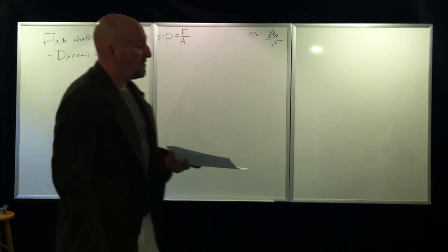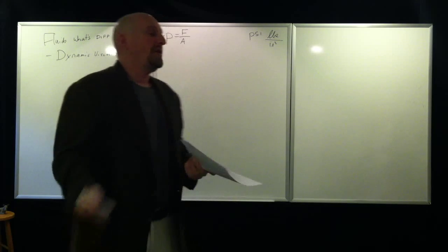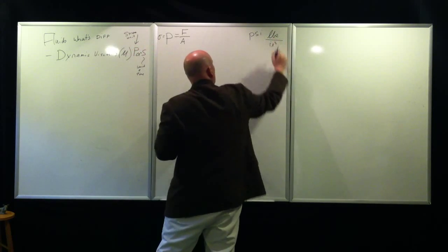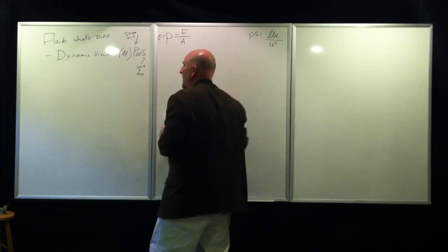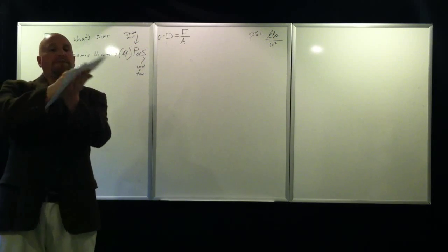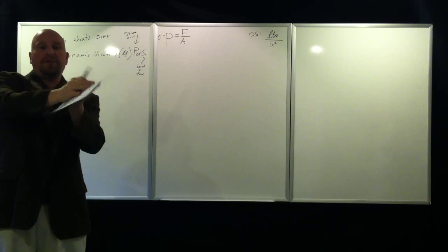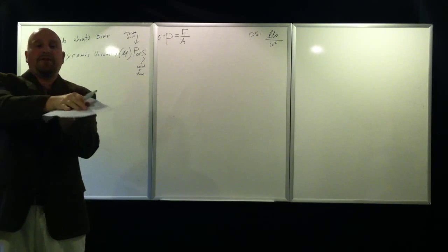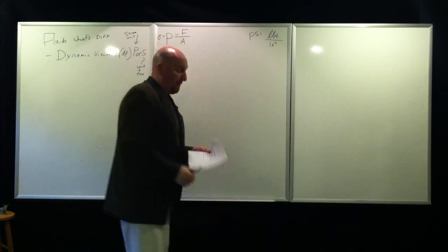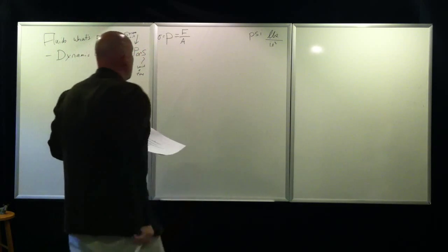Other units of pressure are atmospheres and pascals. Pascals are mostly used in the metric system. But again, it's always a unit of force over an area that the force is applied to. Again, this is normal stress, but I can also put shear or tangential stress to see the result of this particular deformation. There are different types of deformation depending on the direction of the stress compared to the area. It's an important difference. Alright, force.